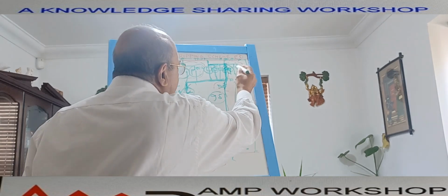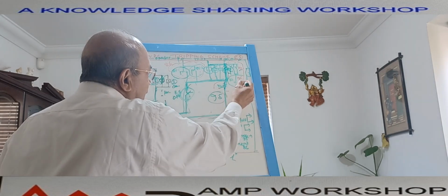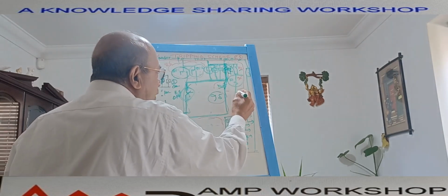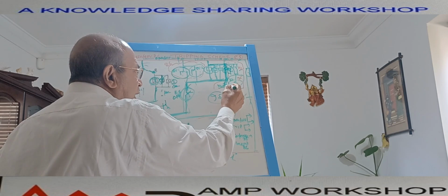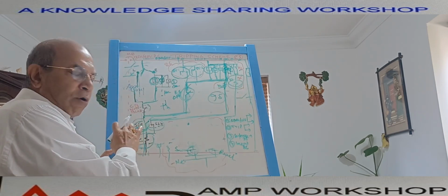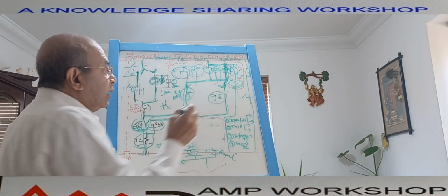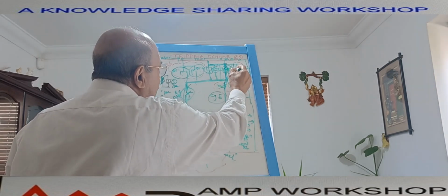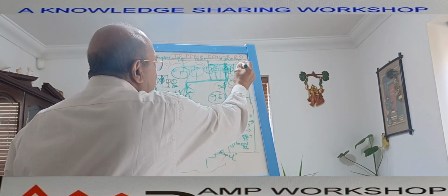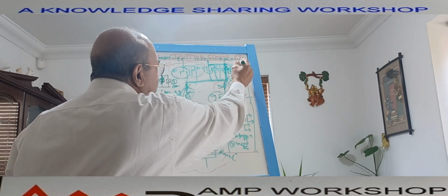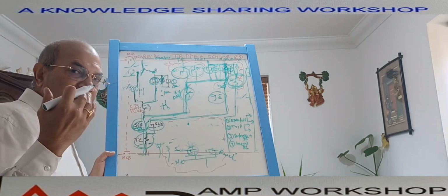So these K1 and K2, the two auxiliary NO contacts we have used over here, are energizing another relay, K3. This K3 relay, suppose this is a NO contact, this K3 is always energized, whether the breaker is open or closed. How? When the breaker is closed, K1 is energized, so this path is through. When the breaker is open, at that time both K1 and K2 are energized, so this K3 remains energized through both the paths. So this 95 is an always energized relay.